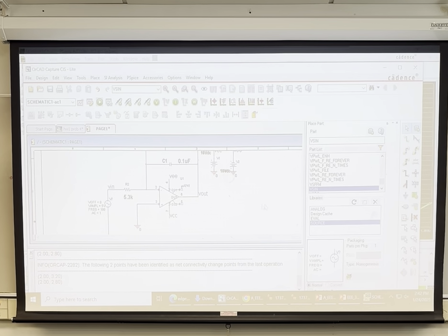Now, you need to add the 30 kilohertz interfering waveform. And the way we'll do that, we'll move this wire, we'll click on this, do a Control C, and then a Control V. We're going to add a second generator in series with the first one. And then we'll add the wire connected.